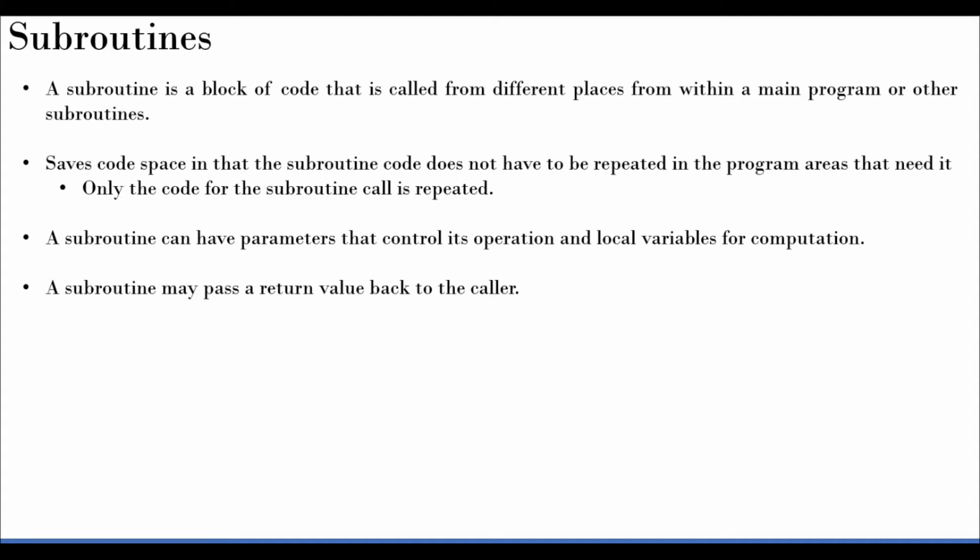So what happens when a function is called from a main function? Let's say I'm in a main function and suddenly I'm calling something which is actually in a subroutine. So the program counter will get the address of the subroutine location, right? But then after the execution of the subroutine, you need to come back to the location in the main code and keep executing the next few lines after the calling of the subroutine. So how does it happen?